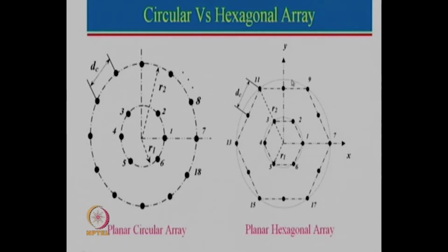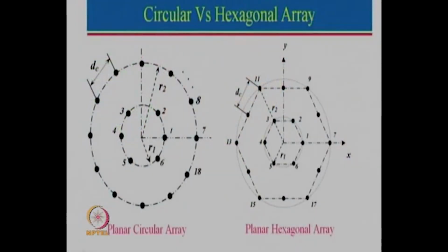So now there are 2 ways to do it. One is we need to find the array factor for this. For a circular array, it is defined in terms of a Bessel function, so you can write this particular function in the form of a Bessel function. Those expressions are available in the textbooks which I had mentioned, Balanis and the Cross book. However, for the other elements which are missing over here, either we can use the Bessel function concept, or we can consider these elements separately and then add them together.